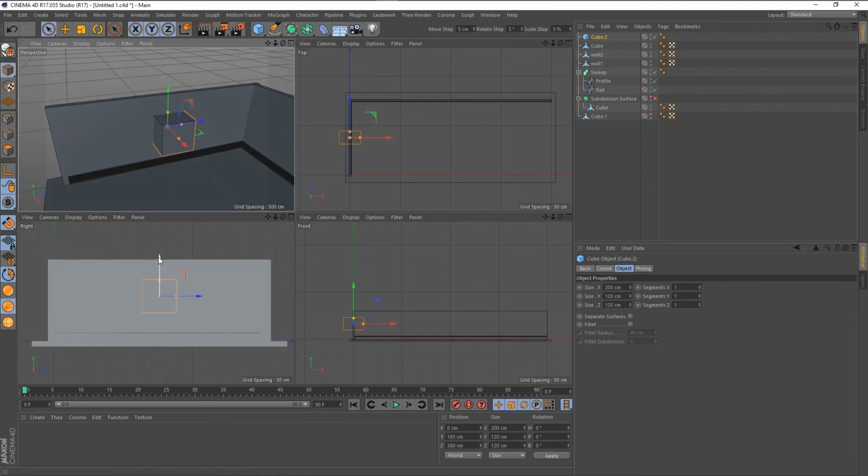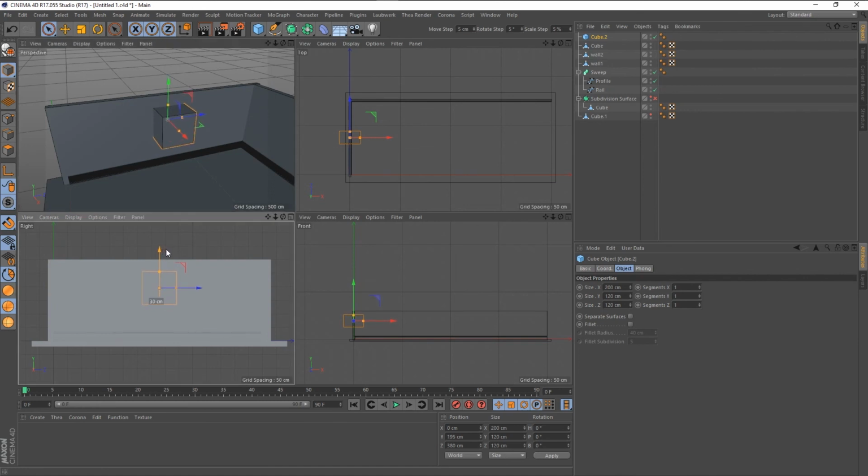And we go into our elevation view, and I'm going to move it up a little bit. So now we can actually set the position for this thing. If we move this, you can see down here, watch this number right there. If I move this, you can set the height either by looking in the viewport, but I look over there because this position is always accurate for the world.